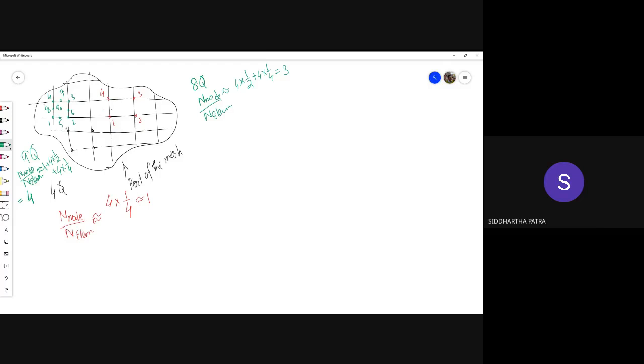It is actually a 25% saving in the number of nodes and the number of degrees of freedom, since each node has displacement in two directions, ux and uy, so 2 degrees of freedom. Therefore it is a lot of saving in computational time.